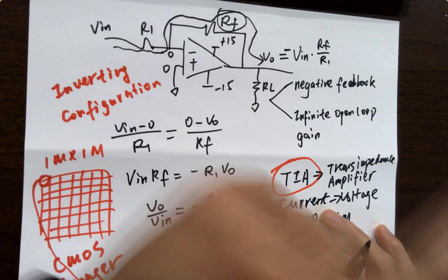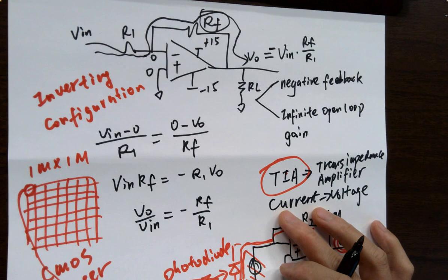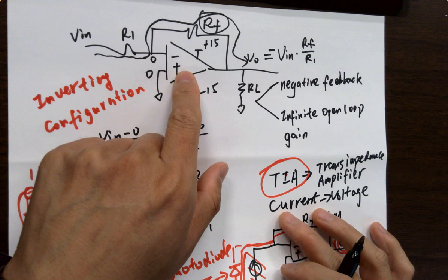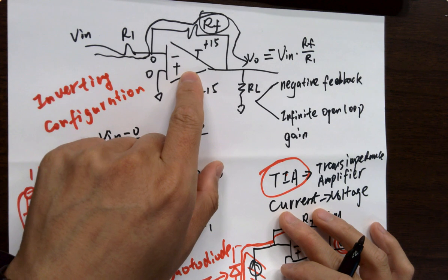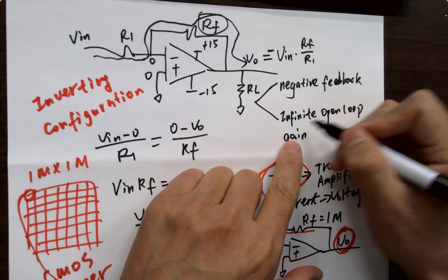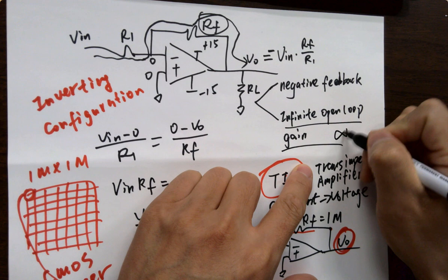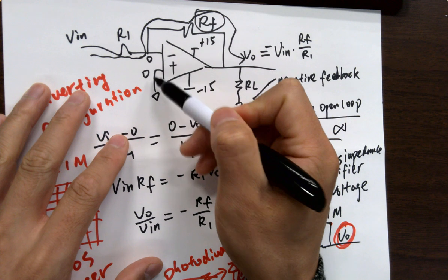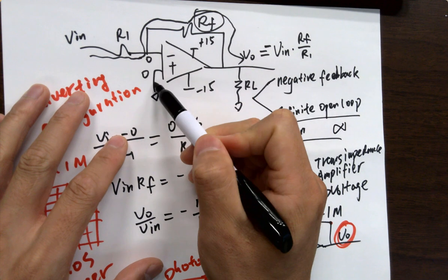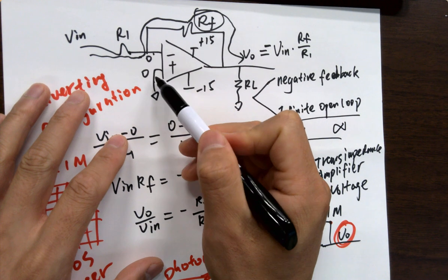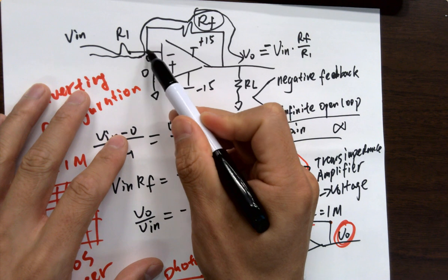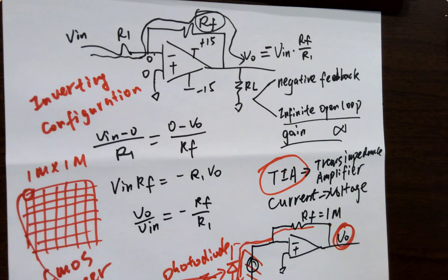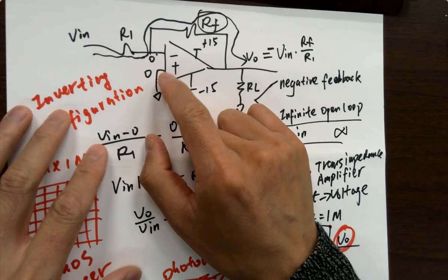I think in all the examples in either tutorial 6 or homework 6, they are all assumed to be ideal op-amps, which means it has an infinite open loop gain, and you'll force these two pins to be equal to each other. So in that case, 0 volts, 0 volts. That's a conclusion. If you see it's grounded, you know immediately this is 0 volts. So this is used for every single example in the homework. Make sure you know that, right?